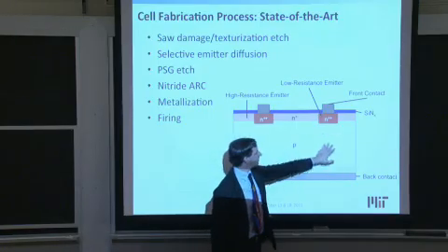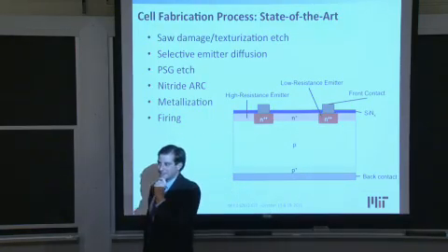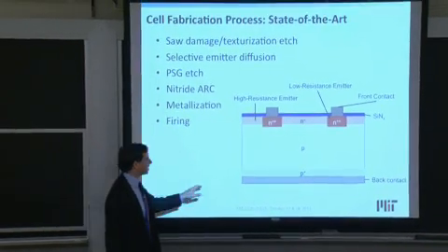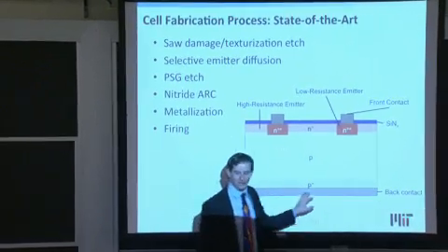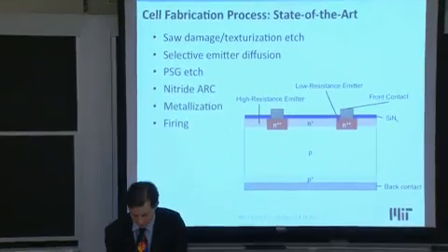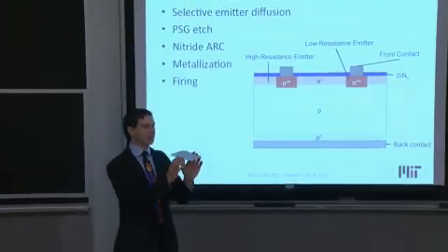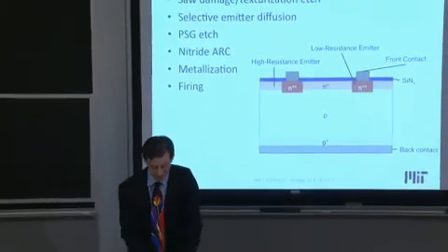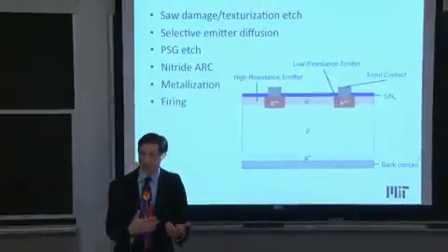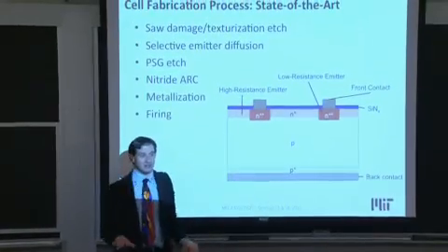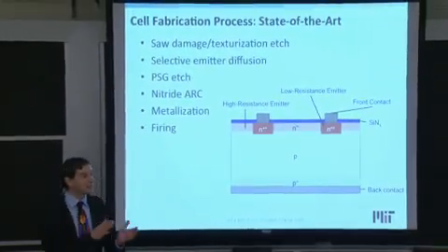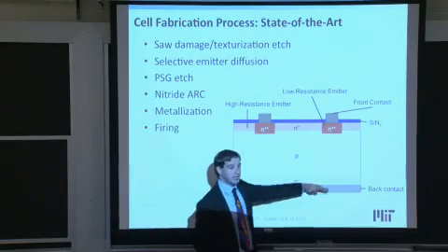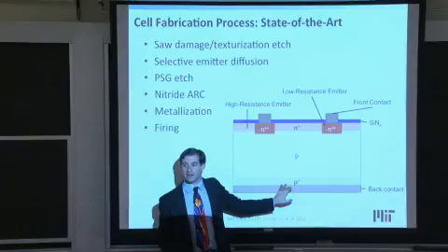And so for each of these different processing steps, somebody had to sit there and think deeply about optimization of different functions. The aluminum on the backside, somebody had to think about, gee, how do I prevent the wafer from bowing too much due to coefficient of thermal expansion mismatch between the aluminum and the silicon? Somebody had to think about, how do I create the right eutectic with the silicon? The aluminum silicon eutectic is at around 577 degrees Celsius, so that you create a good ohmic contact in the backside. How do I diffuse in a certain amount of the aluminum to create this back surface field to prevent back surface recombination?